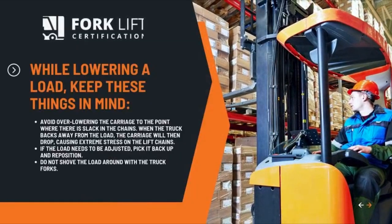Avoid overlowering the carriage to the point where there is slack in the chains. When the truck backs away from the load, the carriage will then drop, causing extreme stress on the lift chains. If the load needs to be adjusted, pick it back up and reposition. Do not shove the load around with the truck forks.